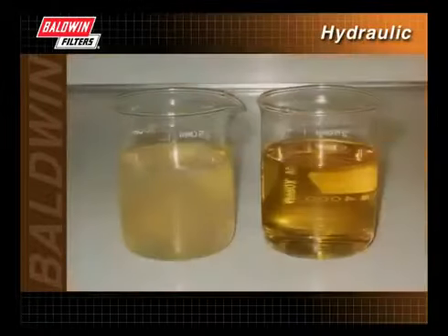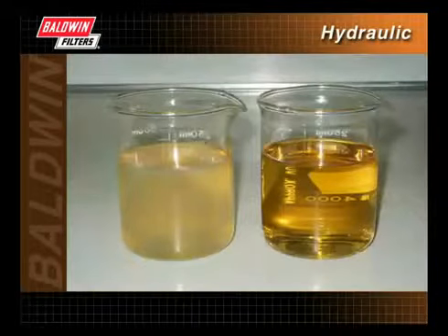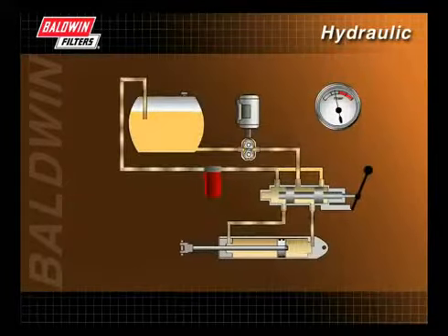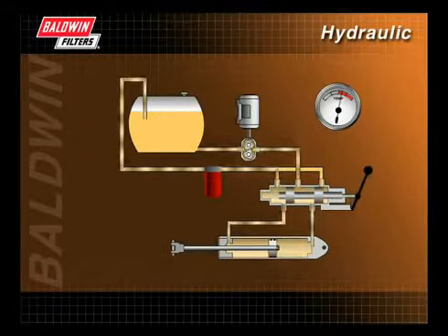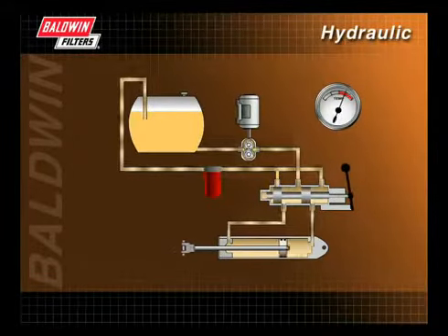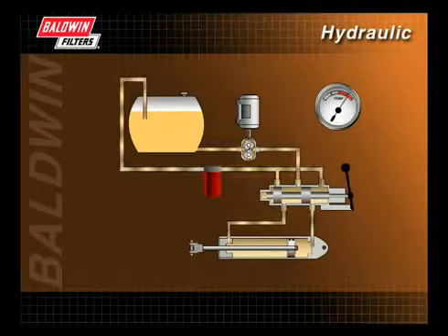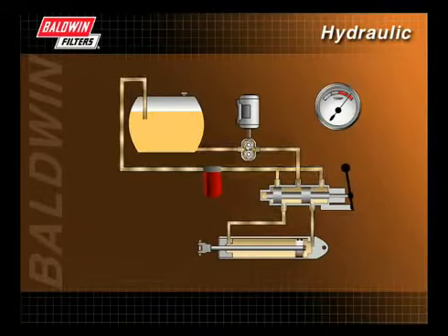Water in hydraulic fluid can cause chemical corrosion. Water can break down fluid additives and chemistry, destroying the lubricating properties of the fluid. Elevated temperatures and high flow rate can lead to further breakdown of the fluids. Elevated temperatures can speed up the breakdown of the fluid, while the high flow rate can lead to electrostatic discharge, which also accelerates the breakdown of the fluid.